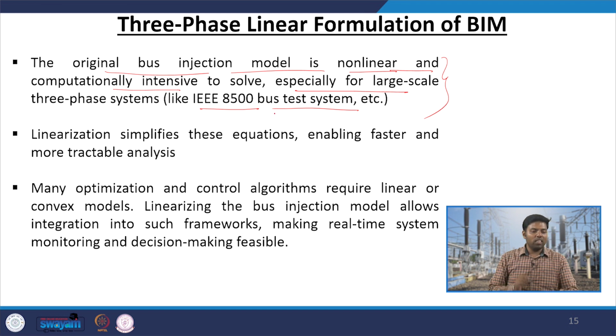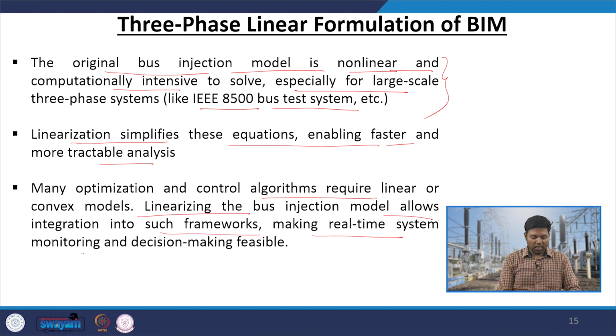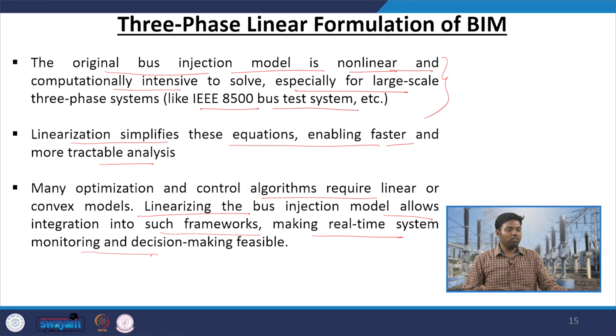That is the first thing. If you want to get rid of this complexity, the only way is that you linearize the nonlinear expressions, that will make your problem solving faster and more tractable. So, how will we do that? For that, we do the linearization of the bus injection model, making real time system monitoring and decision making feasible.